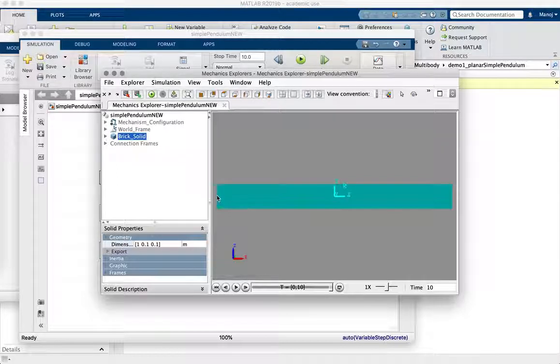We are going to attach the center of that cross-sectional square to, say, a pin joint or a revolute joint. Okay, so this whole thing is 1. This is 0, 0, 0 in the body fixed frame, because that's where the body fixed frame is. This point is going to be minus 0.5, 0, 0.